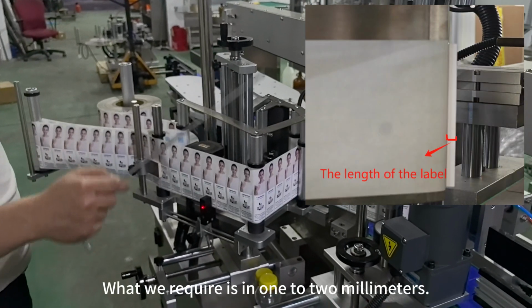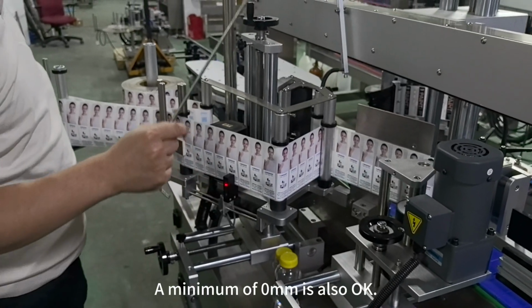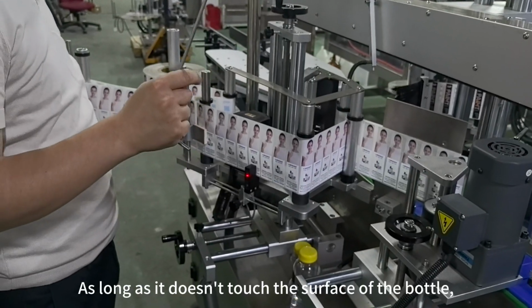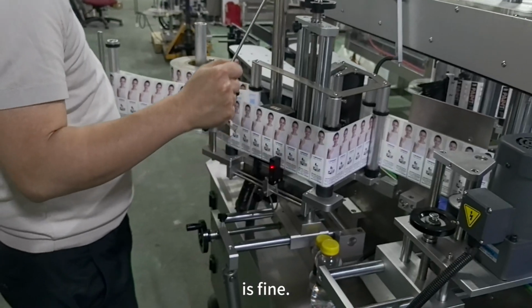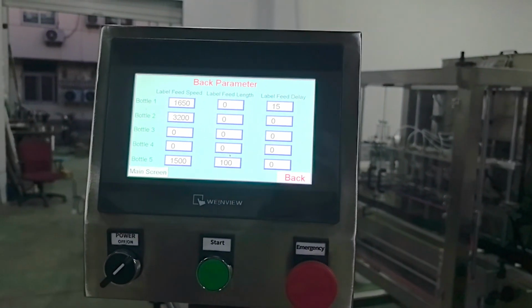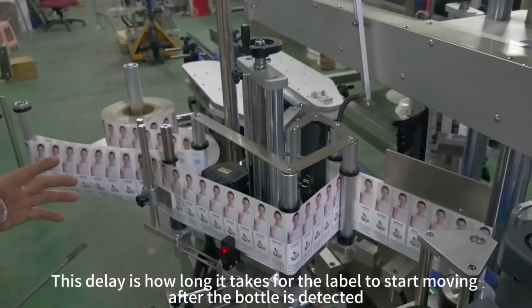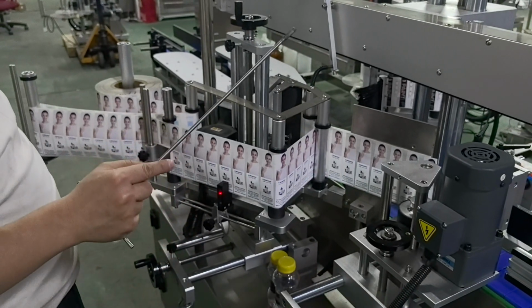What we require is 1 to 2 millimeters. A minimum of 0 millimeters is also okay, as long as it doesn't touch the surface of the bottle. Then label feed delay is the delay in distributing labels. This delay is how long it takes for the label to start moving after the bottle is detected.